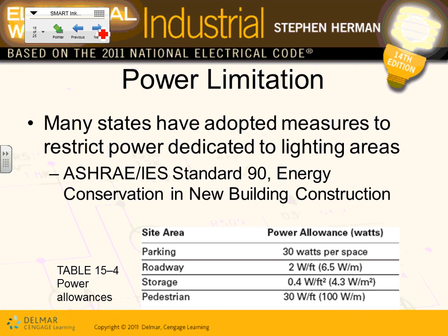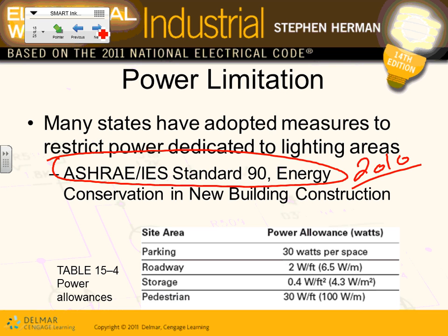This is what we used, ASHRAE, guys. This is the energy code ComCheck that I use with Chad. The one that we use is ASHRAE 2010 for our project. We were lucky because we have LEDs, so we can meet it. We have multiple levels of switching for the auto switching occupancy sensors. And with ASHRAE, if you have LEDs and you have an auto means of controlling your lights, you almost always meet the code.